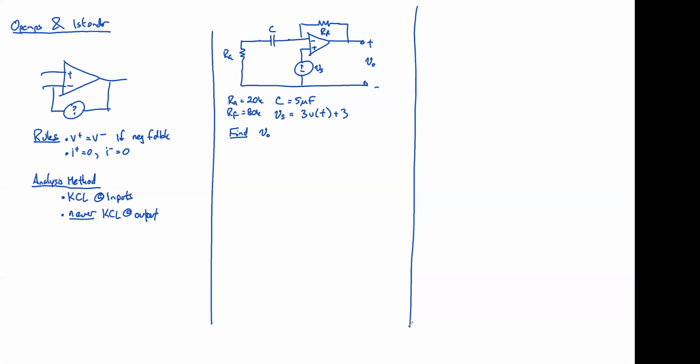You guys remember the steps for solving any first order circuit? Let's hear it. Who hasn't said anything? Philip. So the first step is to find V out when the time is less than 0. Right. To find VC naught, or equivalently I L naught. And you'll do that, like you said, for time less than 0.